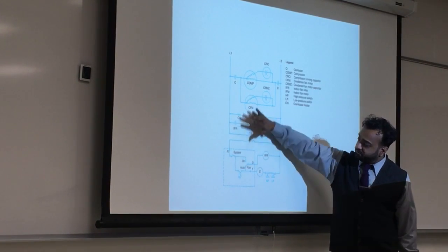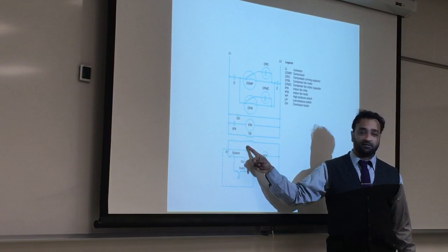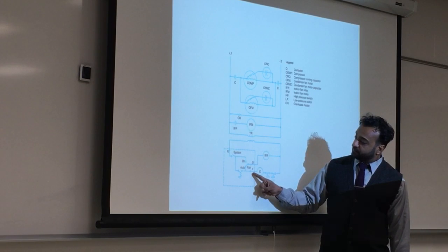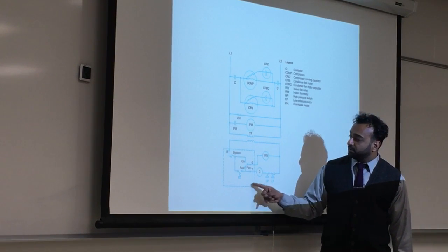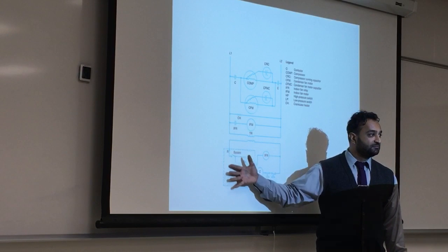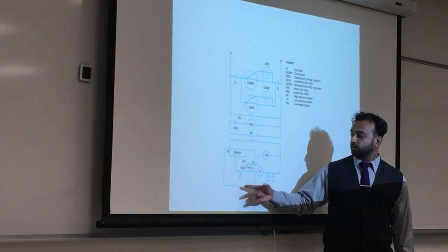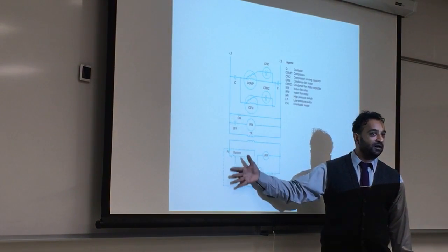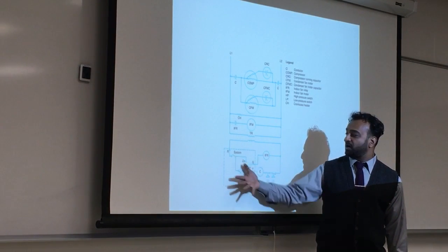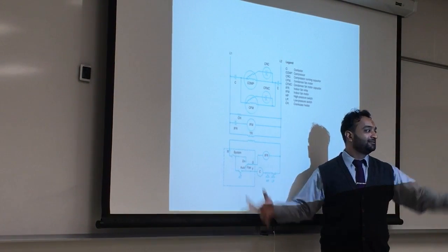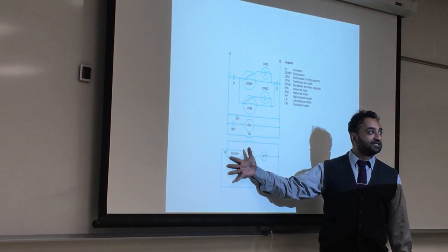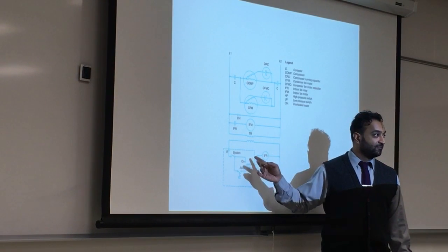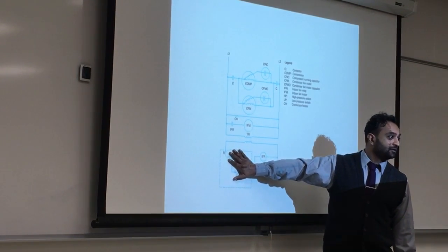Let's look at the secondary circuit by itself, little by little. Voltage coming in, 24, same thing. And we have a few switches here. If you notice, they put all these into a dashed square line. What do you think this is? This is a group together, which resembles what? What has R, G, and Y, and fan, and O2, and system? Connections. Yeah, but what do you think the whole box is here together? Thermostat, excellent. This is my thermostat. I can ignore the whole thing, I just cover it up and say it's a thermostat.